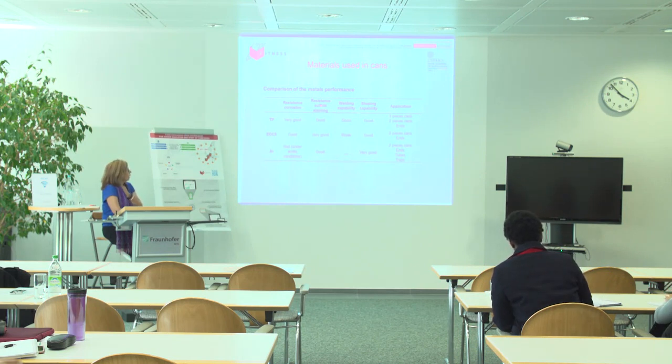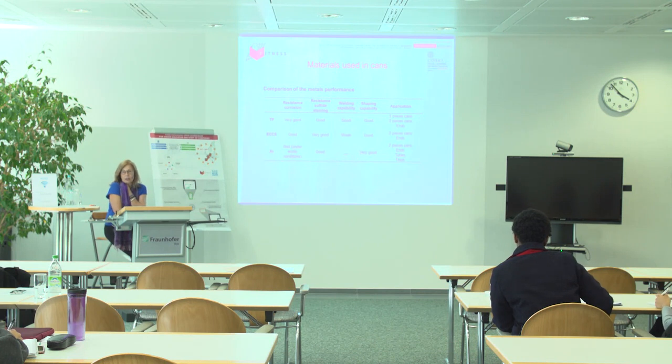It is also good in resistance to sulfide staining. Sulfide staining is a reaction that occurs in metal packed products when the food product has sulfur in the combination, and we have tin or iron in the can, and the sulfur combines with the tin or with the iron, and some spots appear inside the can.